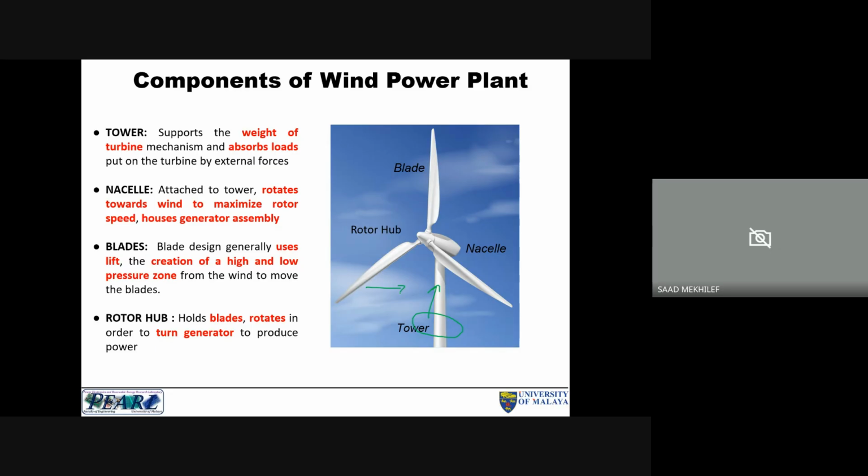For example, if I have 7 meters per second at this height, and I increase the tower height by another maybe 3 or 4 meters, what will be the wind speed? If it jumps from 7 to 9 meters per second, a difference of 2 meters per second, I put it in the power equation and find the amount of power that I can get, what the cost is, how much this power can be sold for, and what the cost is to increase the height by 3 meters.